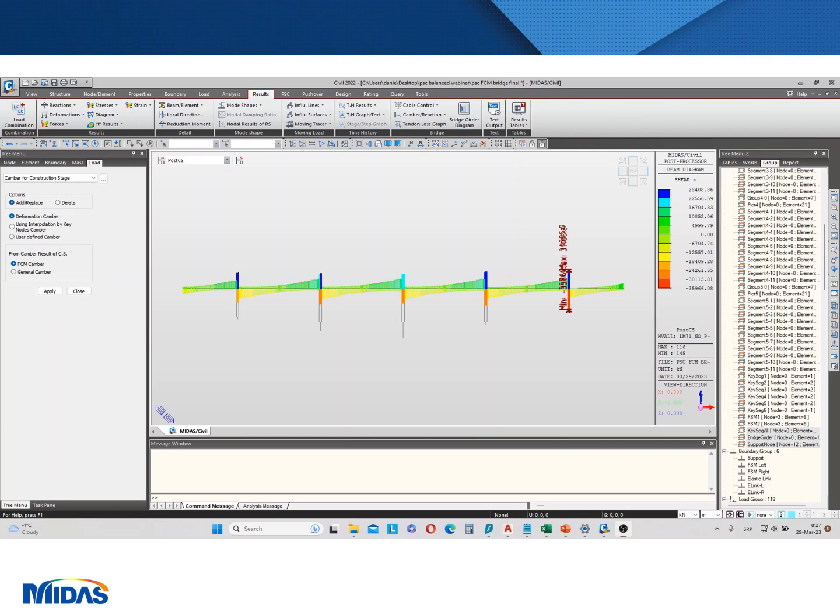So this is the point. Actually, we can add it to report browser, name it, and we can insert it as a dynamic report change. And let's say, for example, I want to change the force in this tendon. I make it lower. I don't have to picture everything, to take these charts or something. I just need to update my dynamic report and it updates automatically with it. Also, you can save graph as image, which is not dynamic then, and you can also save it as a text and then use it to maybe generate graphics in Excel. It saves as a CSV file.